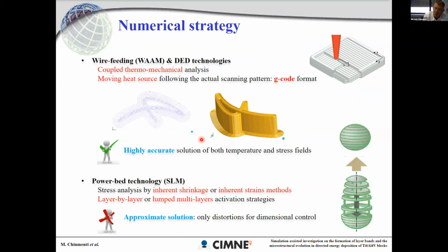So we are following the heat source with its movement, and in fact we are reading exactly the same path as the machine does. So we are reading the G-code format of the machine, and we are reproducing this in our simulation tool. So we are looking for a very accurate solution of both temperature and stress field.